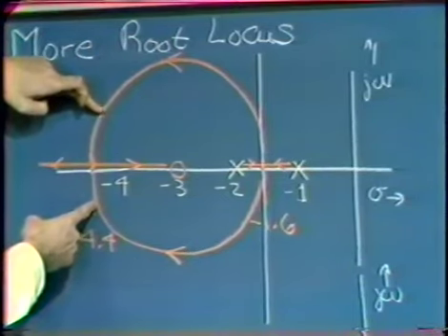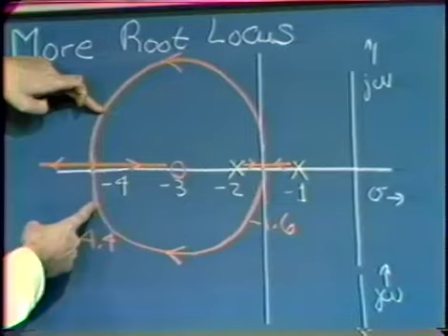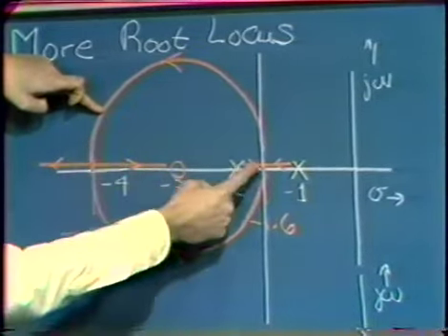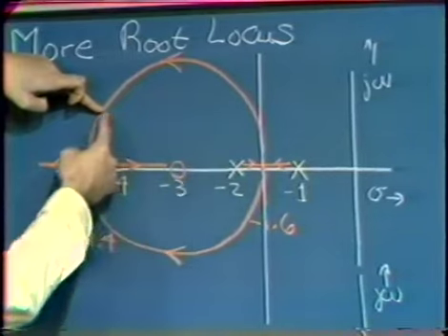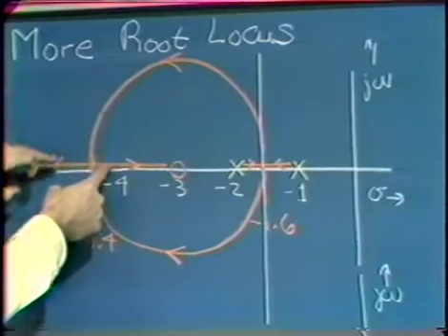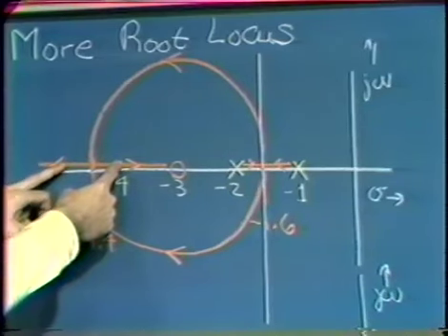If we, for example, turned up A0, F0 to this point, we'd have quite a high value for damping ratio, a damping ratio maybe of 0.8 or something like that. And still further increases in A0, F0 result in two real axis poles.